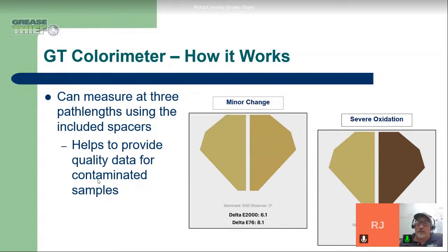And that's another thing we've been getting involved in, Richard, the testing of different kinds of greases. Because if you turn back the clock to the early days of the robots' growth, pretty much one grease was being used. Then there was a short period of an alternate grease. But now we're seeing more kinds of greases. I think some different grease manufacturers are coming onto the scene with products they say can be used. And certainly it creates a potential for mixing.